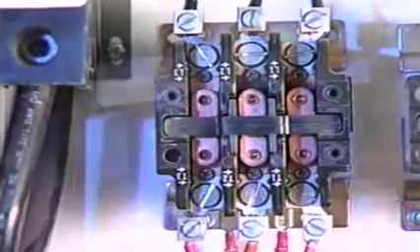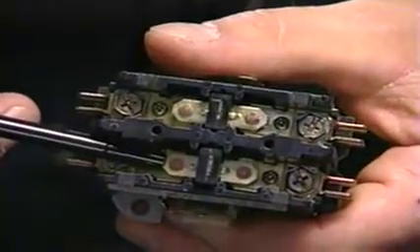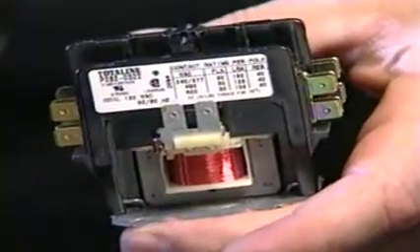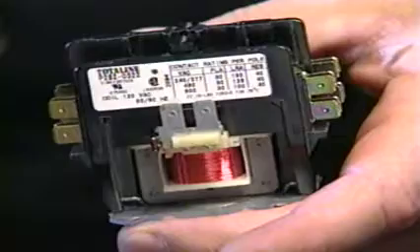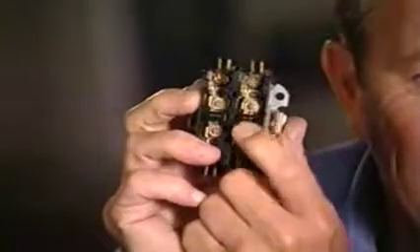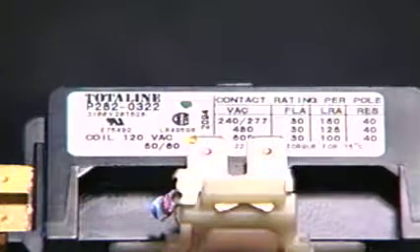The two main components of the contactor are the coil and the contacts. The contactor coil generates a magnetic field which pulls the contacts closed, energizing the system load that's being controlled. Contacts on the contactor are connected to an armature that helps ensure that all sets of contacts open and close at the same time. Contacts are rated by their current carrying capability. Large loads require contactors with a high current rating.